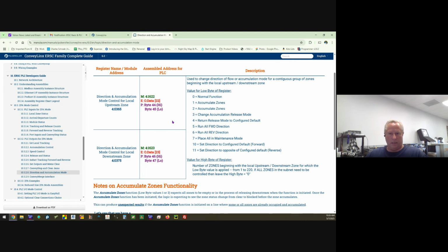One thing to keep in mind, these commands are ZPA commands. So in your 50 card network, card number 20 is in PLC mode. And you said node 1, command 5, run the motors, number of zones 0, meaning every zone. Enter. It would go all the way to card number 20, which is now PLC mode, and stop, because PLC mode does not accept ZPA commands or pass them through its registers downstream.